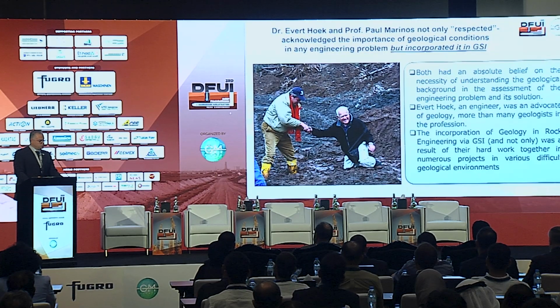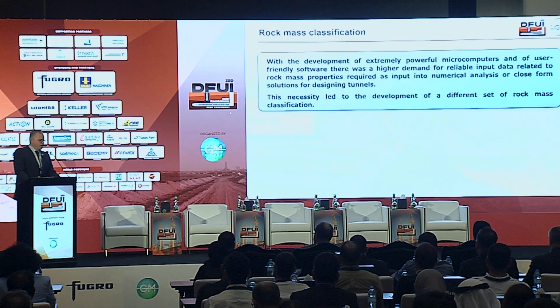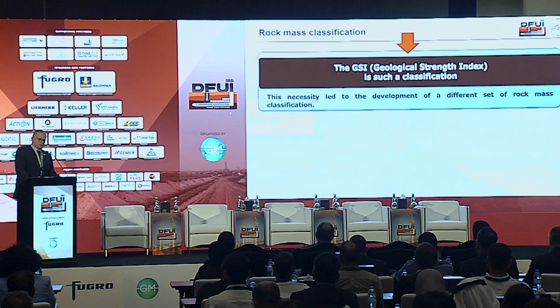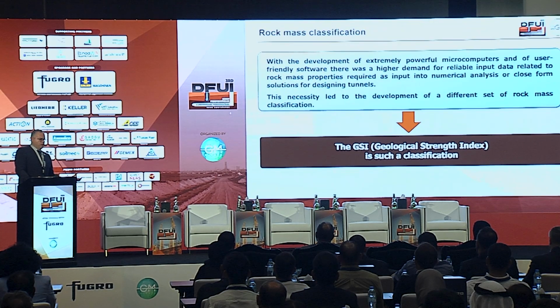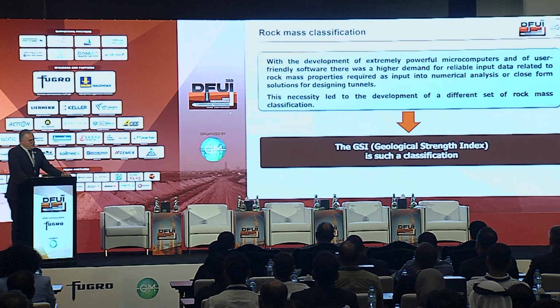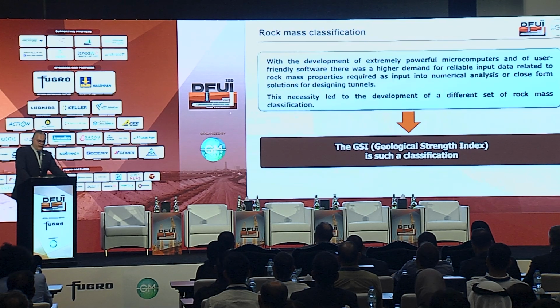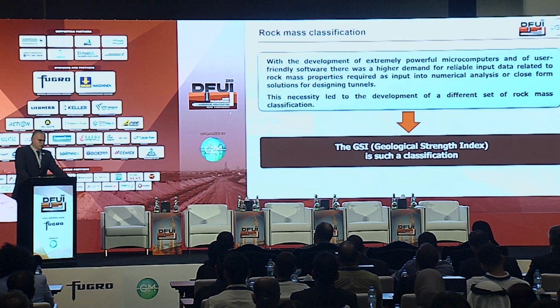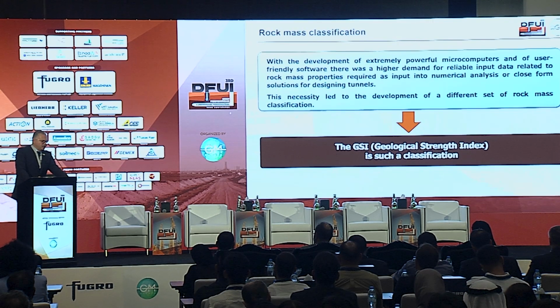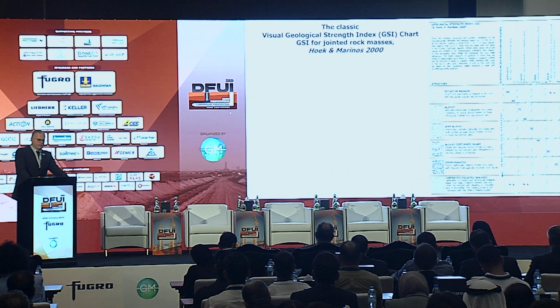And of course, they have compiled many, and together we have worked a lot in order to characterize different kinds of geological environments. So nowadays, we need strong inputs. So we need to characterize and find the strength and deformation of the rock mass. So the GSI is such a classification used in the Hoek-Brown failure criteria.